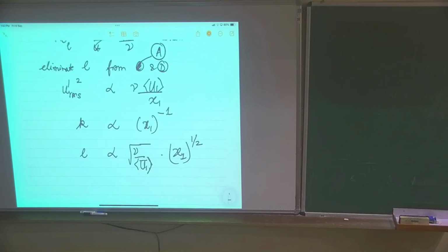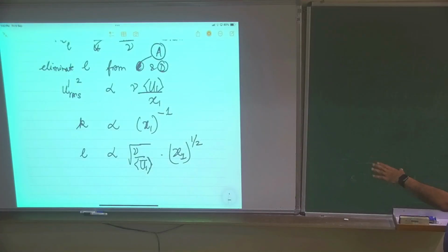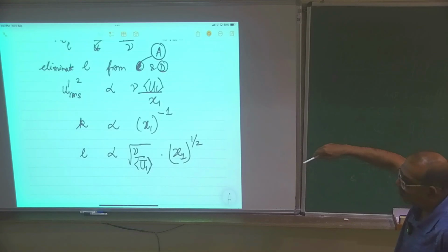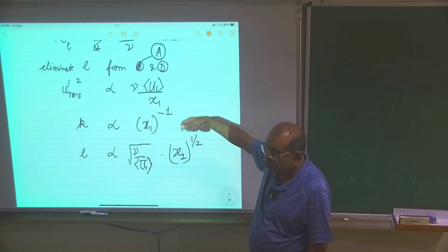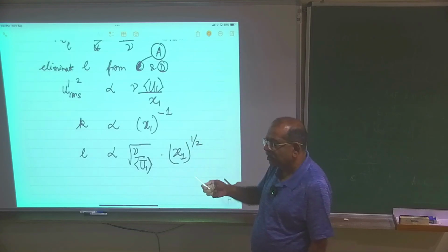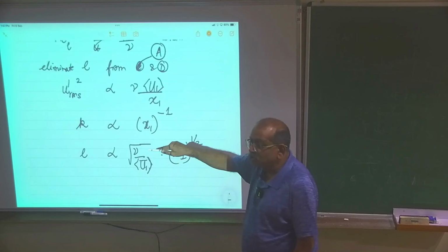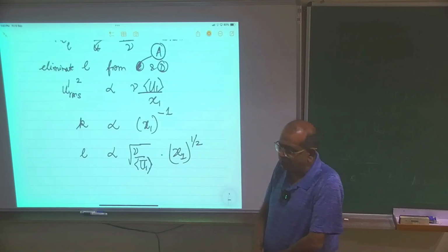According to this, L only increases, but you are saying when dissipation kicks in, it should go down. This limit is probably till, I think assignment 1 has one such problem. Here it is constant, but eventually, as kinetic energy decreases and U prime goes down, somewhere you will get a limit where U cube upon L is equal to C nu U square over L square. When you equate these two, this will give you some sort of a limit.